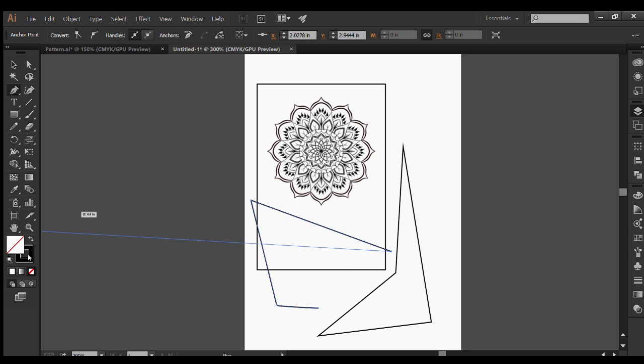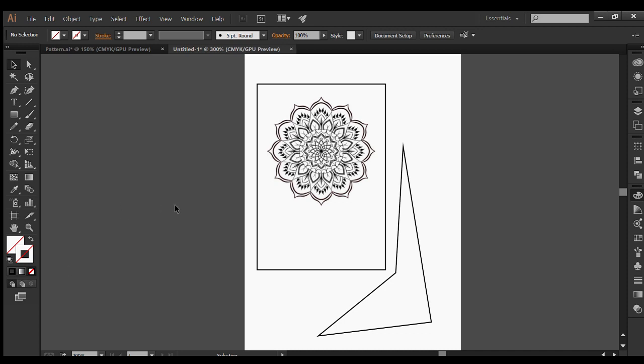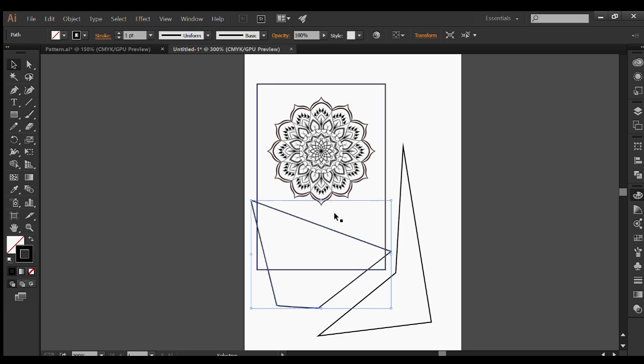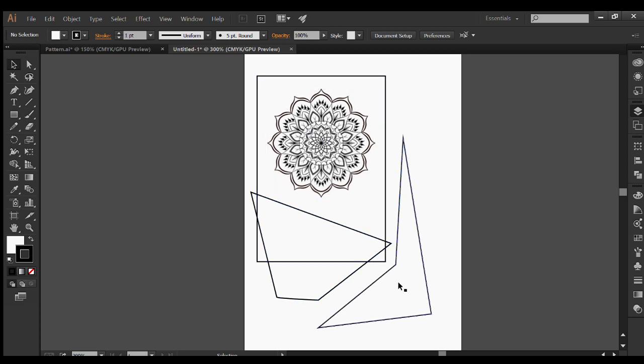But you also have to be careful, because you can also set the stroke color to none. So when that happens, you actually don't see anything. But if you hover there, you still see the shape. So it's still a vector file. The machine would still read this vector file, but it's something that you just have to be careful with. And whenever this happens, you could always check the layers. Everything that you just drew, if we click it here, actually gets highlighted. So all of these are vectors whenever you're drawing.